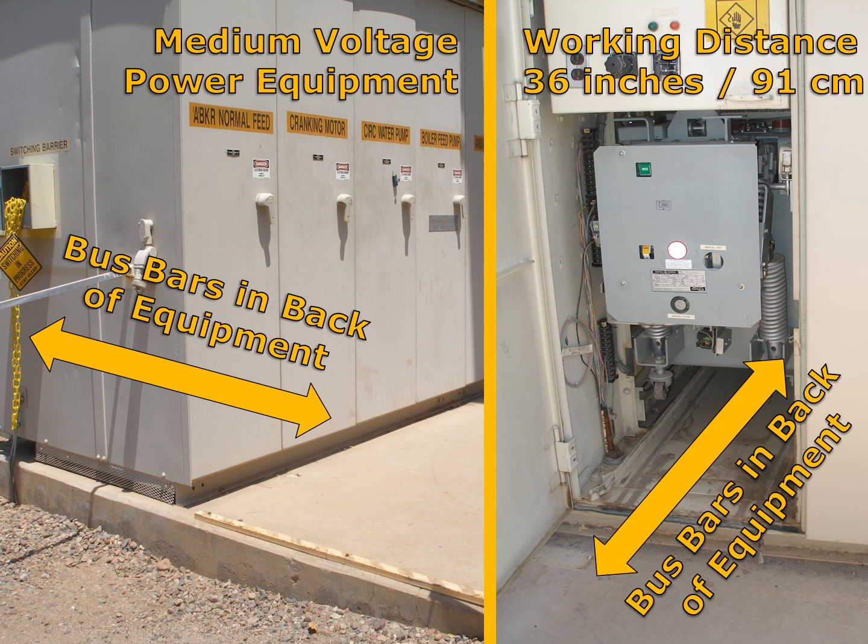Another consideration is if you have equipment like this that may be accessible from the back. If there's ever a possibility that someone may access the rear of the equipment while it's energized, you may want to rethink this 36 inches. Because 36 inches assumes that the energized conductors are near the back of the equipment. If you're actually accessing the equipment from the back, it's going to be a lot closer. The bus will typically be very close to the rear of the equipment, and 36 inches in that case wouldn't be a suitable distance to use.